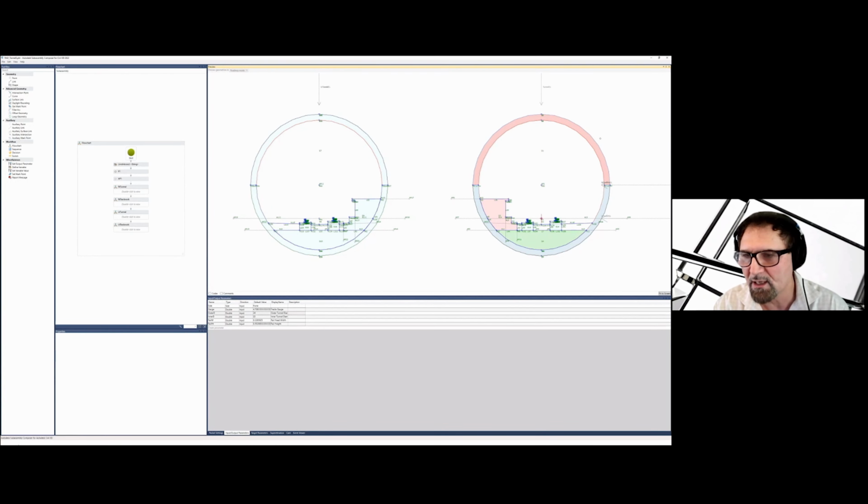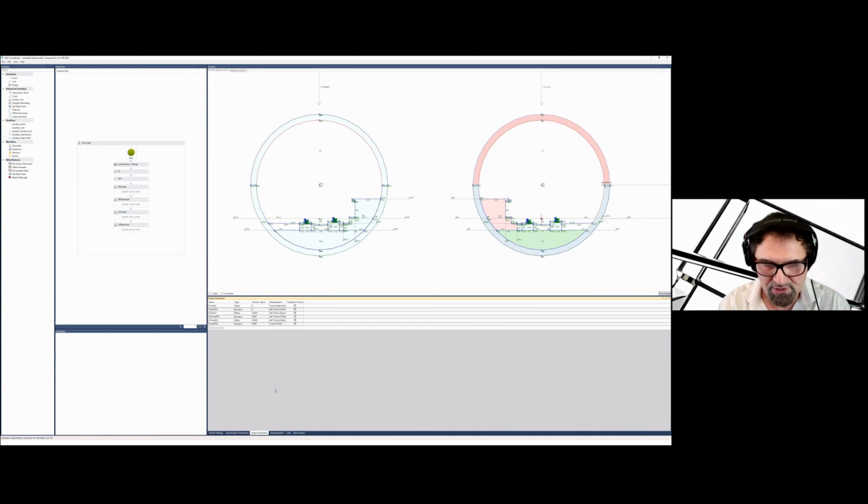Now I'm dealing with tunnels of a larger structure, whereas the track alignment relative to the platform or emergency maintenance walkway is maintained. Also, the elevation difference between the tunnel center line and the track top of rail center line is maintained. One other thing that I really enjoy using with Subassembly Composer is target parameters.